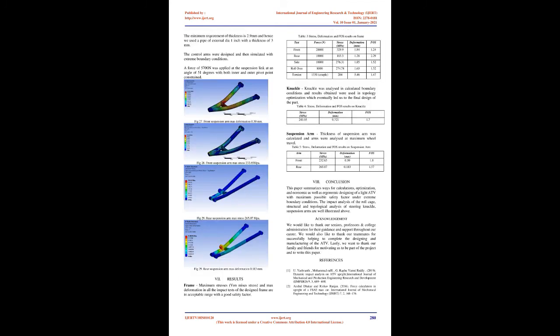FUB,H equals 1281.34 N in a horizontal direction towards the wheel center. 3. Force on steering arm. 618.69 N in a horizontal direction towards the wheel center. 4. Moment on caliper mounting. A moment of 43,910.73 Nm in clockwise direction.